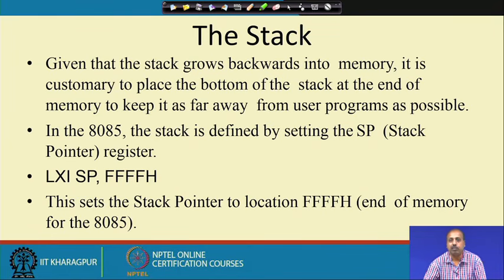Like in the previous example, I said that my memory ranges from 0000 to FFFF and I put the stack to start at 8000 hex. Now, there is a possibility that some user program data or program code will clash with that stack. Just to avoid it, it may be a safe practice to have the stack initialized at the very bottom of the memory. So, this stack may start at FFFF hex, and in 8085 the stack is defined by